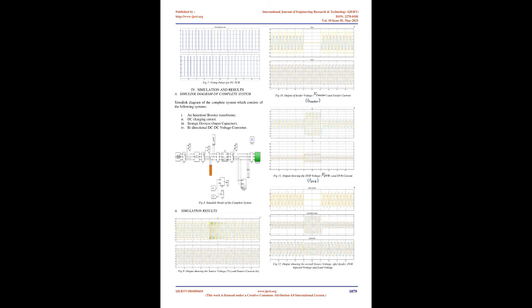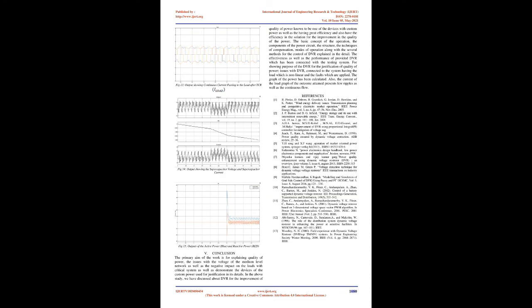The principle as well as the substance of the harmonic current flowing in the reactor, I_T, can be expressed as a function of the angle α. It is obvious from equations 4 and 5 that the TCR is able to control the current from the zero level to the extreme level, because it is a variable reactor controlled with the help of the delay angle α. If there is an unbalanced three-phase system, then the triple-n harmonic currents, 3rd, 9th, 15th, etc., start circulating in the delta applied to the TCRs and are restricted from entering the power system. The values of the other harmonics can be produced with the help of the TCR.